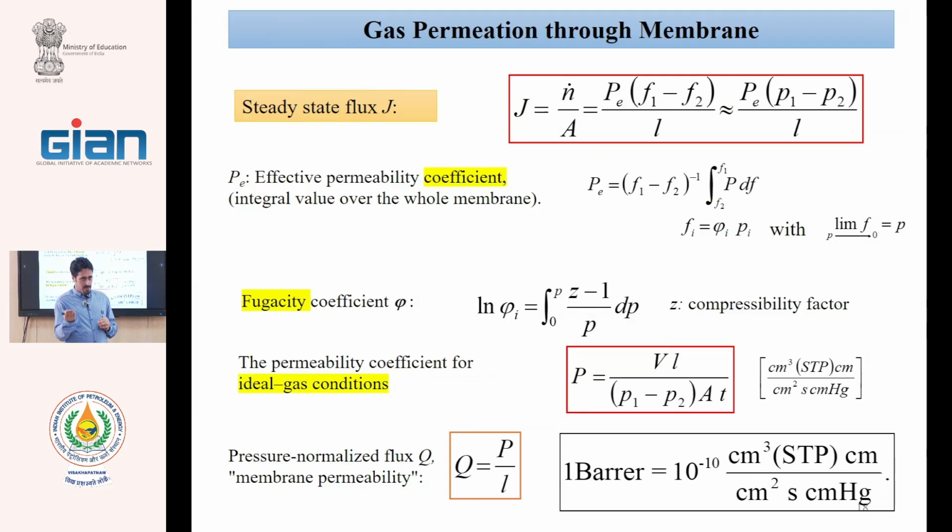We have a commercial polymer and the gases carbon dioxide, nitrogen. My barrier should be 10. I obtain 12. What is the problem in most cases? In most cases, humidity. When the polymer absorbs the humidity of the environment, the polymer can swell, very swell. And when it swells, we have an increase in the free volume in the pores, and the flux increases.